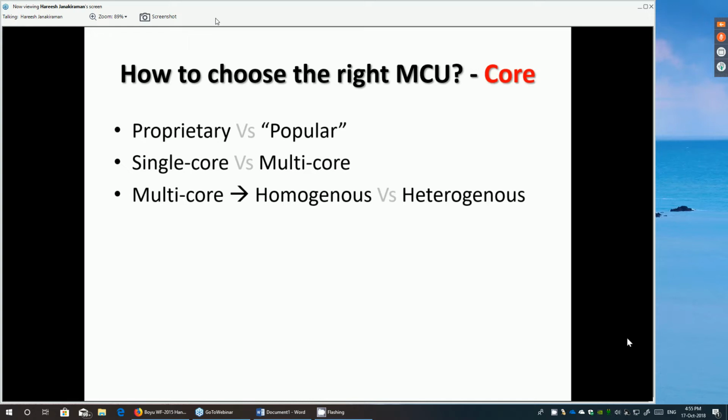However, if I have a chip whose architecture is optimized, and what I mean by architecture is optimized is there may be parallel pathways between the CPU and the memory. I'm saying I need to multiply two parameters, right? So the CPU may have two parallel paths, one path to memory one and one path to memory two. Therefore, the CPU may be able to fetch both the parameters that need to be multiplied at the same time. Okay, so this is what I mean by architecture is optimized. Primarily, you may have more than one path to access data.